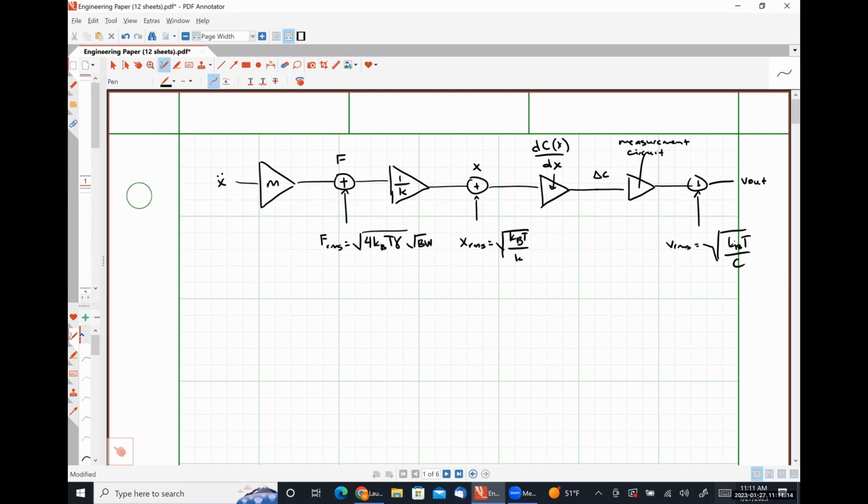The acceleration goes through all of the mechanical and electrical conversion processes into an output electrical signal that I'm going to have you guys calculate. So that's going through the signal chain in one direction. And then I'm going to have you calculate the input referred noise acceleration for the whole thing, effectively referring everything to the left-hand side to give me a particular signal to noise ratio. Or actually, what I'm intending to ask you is what is the minimum acceleration that this system can measure if you need a signal to noise ratio of X, okay?